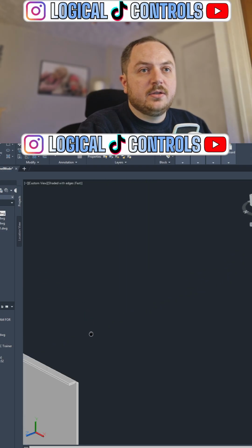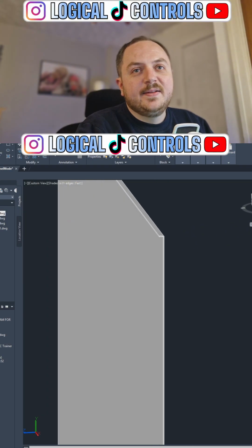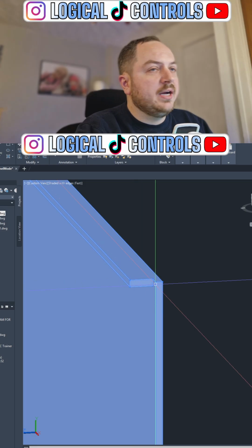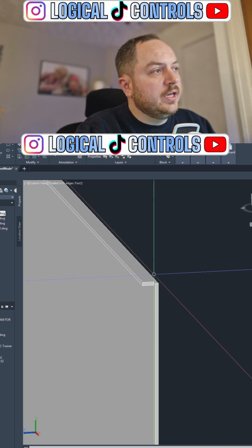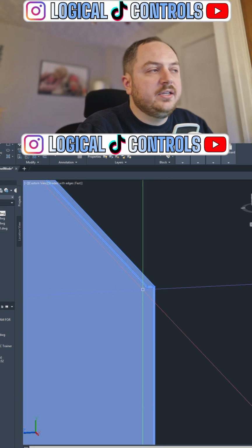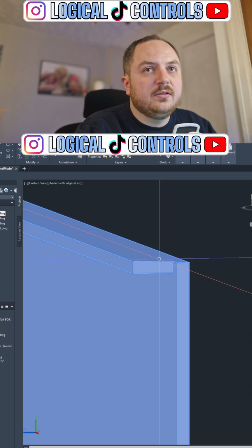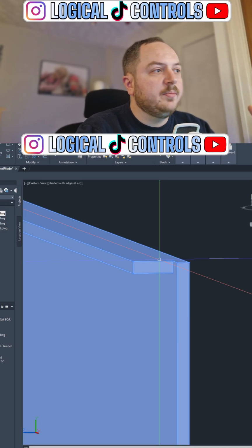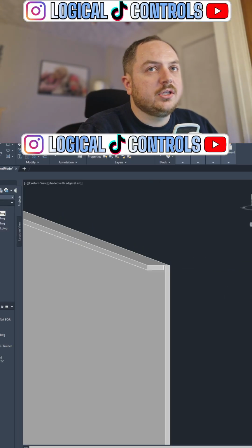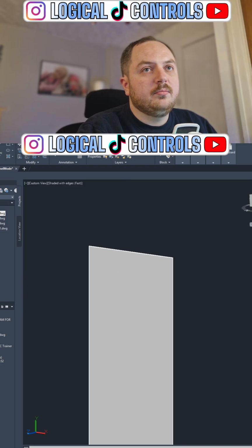You can see on there, it's hard to show it because it's so light. But the metalwork folds back on itself, and I could fillet it and all that and make it nice, smooth, rounded folds, but you don't have to. When you start filleting stuff, AutoCAD has to store more information in the model, and if you've got a big panel, it can really slow down your model. So we're going to do that for basically everything.